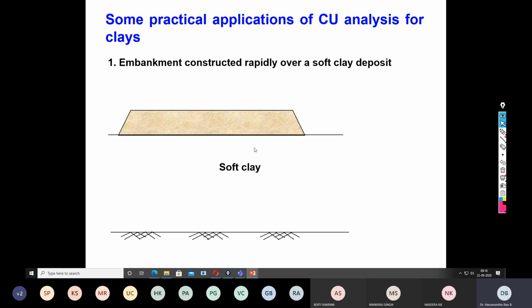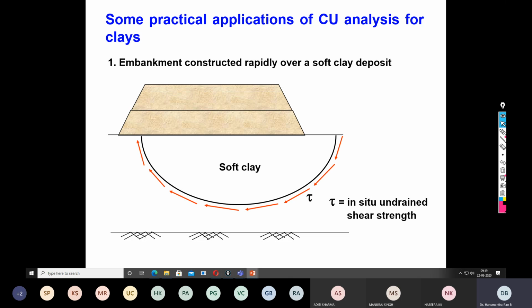So during the construction phase, what happens to the shear strength parameters? And during the consolidation phase, what happens to the shear strength parameters? And after the consolidation, what happens to the shear strength parameters? So initially, this is the possible shear failure development beneath the embankment.